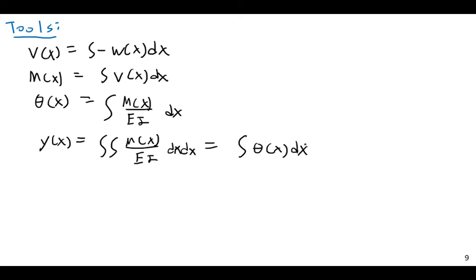And for this, the same sort of rules would apply. If you have discontinuities, you're going to need to break the beam into a variety of pieces, where each discontinuity serves as the boundary between different zones of integration.